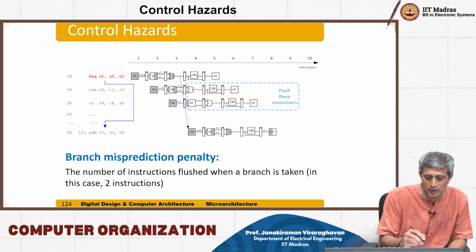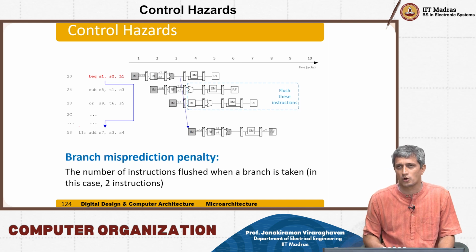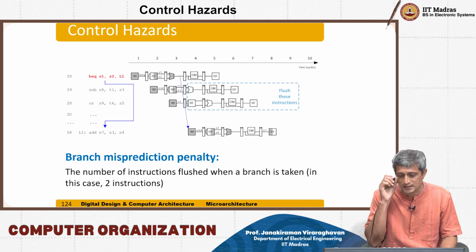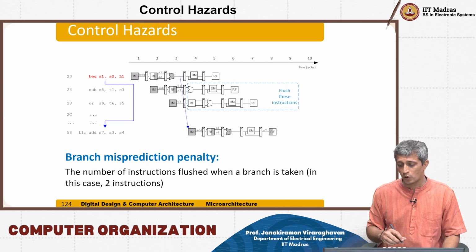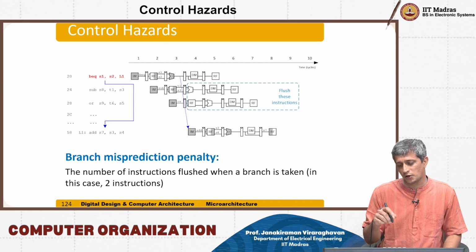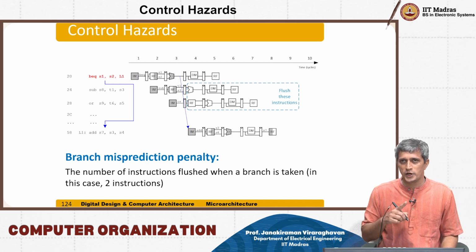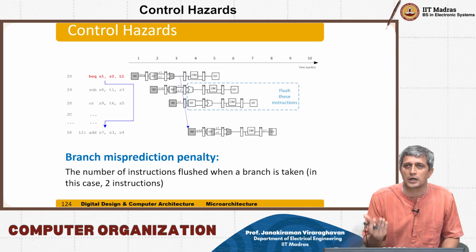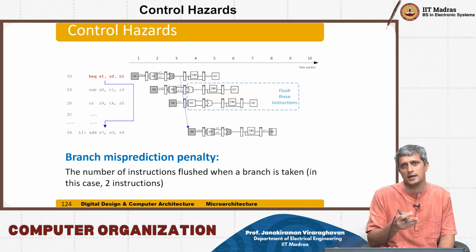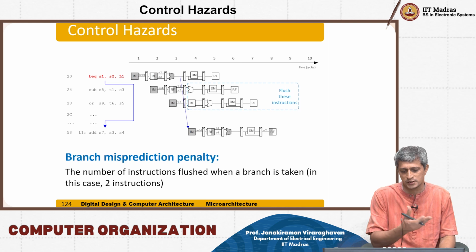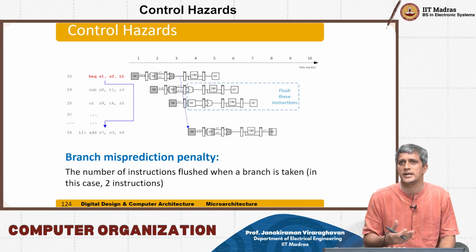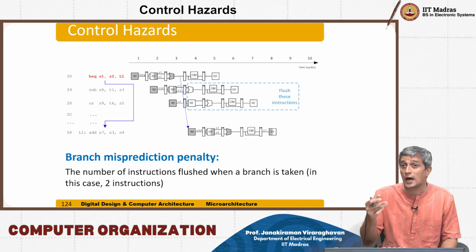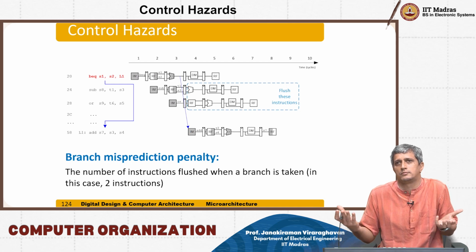So that's what this L1 label is here. You're loading the PC with that new label, and then you're executing add S7, S3, S4. So therefore what is going to happen is, after clock cycle 3, in clock cycle 4, you need to flush those two instructions, and you have to start from the fetch of the add, which is sitting in some address 58, hexadecimal 58.